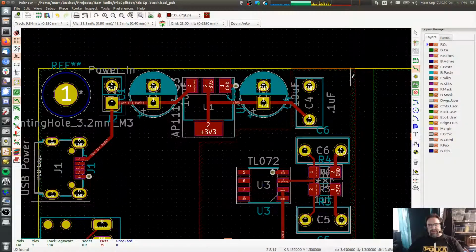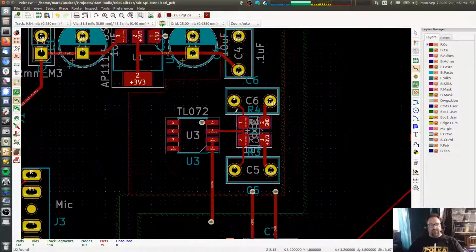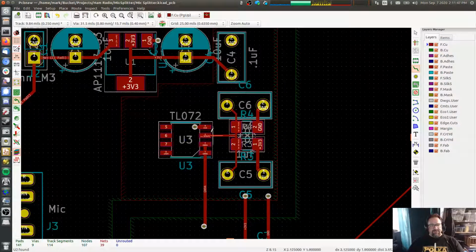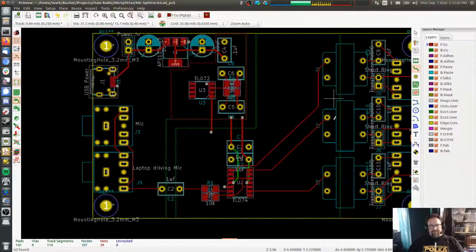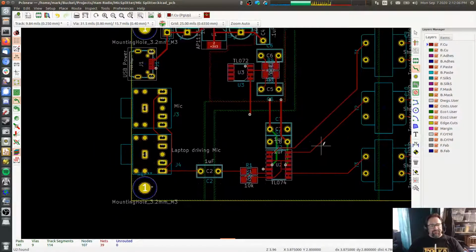Then the output of that goes to this red pour, which is the 3.3 volt pour. From there, that goes into half of an op amp that is just a VCC over 2 reference for my analog ground. And the output of that analog ground goes to this ground pour. This big ground pour here, which is our ground A signal.